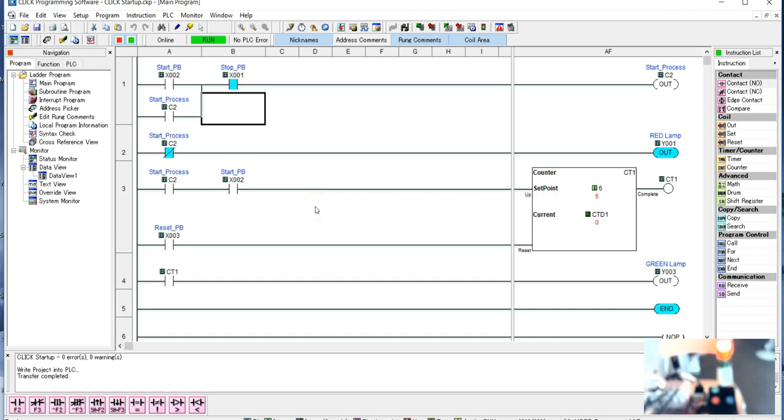Normally that's how you do it for any digital inputs for push buttons, because you really don't want it to matter whether you've got your finger on there for 1 second or 1 minute. You really want to do it the instant that you press that push button, but that's a little too advanced for what we're doing.